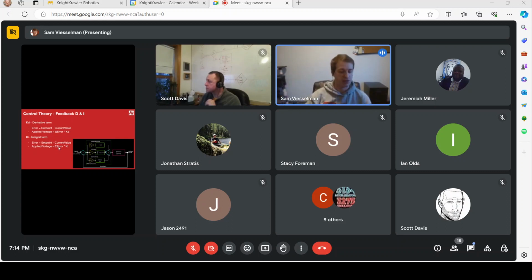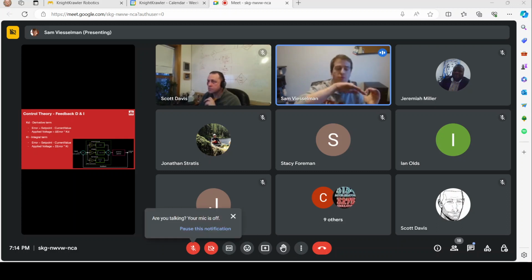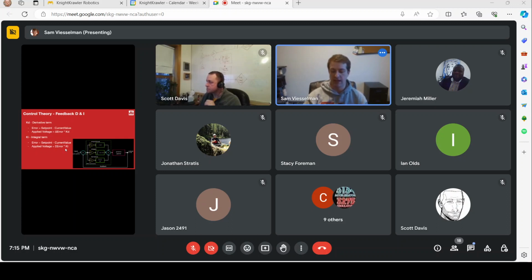This is useful if you have a mechanism that you're trying to set to 80 RPM and it hits 70, 75, or 79.5 and sits at 79.5 for a long time. Over time, because we're summing the error, adding it all together, eventually Ki is going to take over and say, okay, it's been in error for a long time, I'm going to apply more voltage. The only problem with this is that because there's a time term involved, it's really, really easy to get unstable.